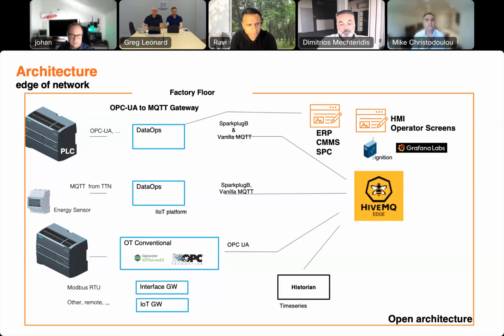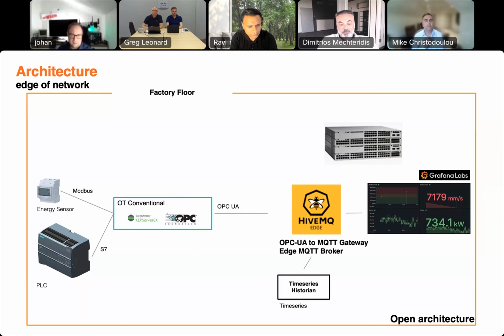I have a PLC and I have an energy sensor. And these speak serial port protocols. They might be speaking Modbus or S7 or other PLC related protocols. We have a very common element here, KEP server, which will allow me to have all the native PLC drivers converted into an OPC UA server, for example, and I will utilize this in the demo. I will use OPC UA, and I will have HiveMQ's Edge product to subscribe to the data coming from the PLCs and the energy sensor.